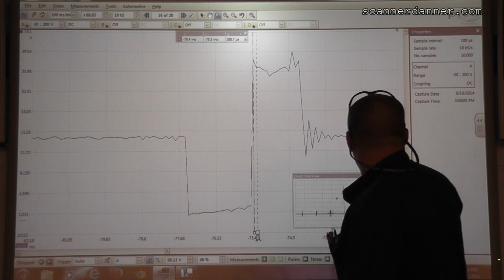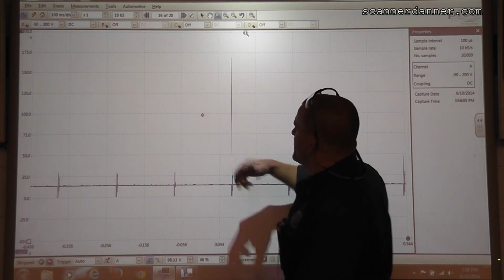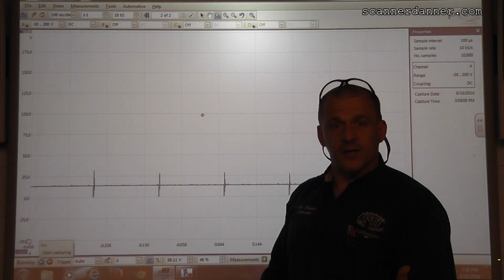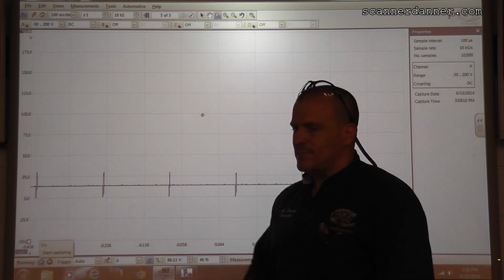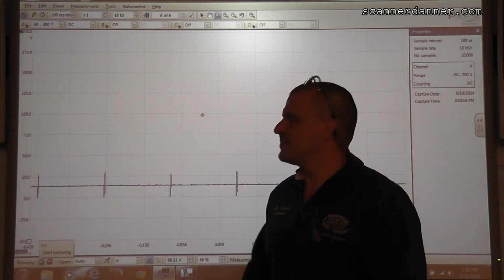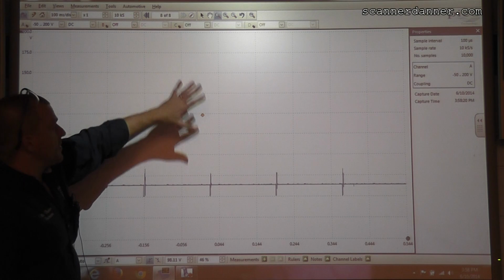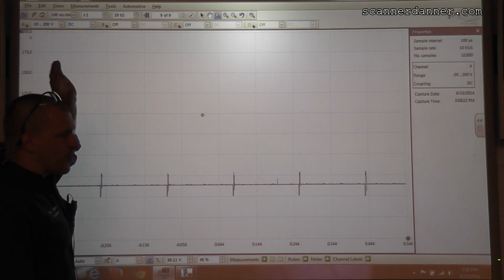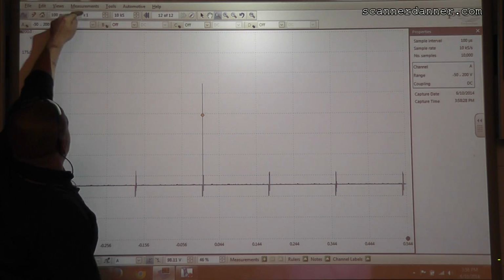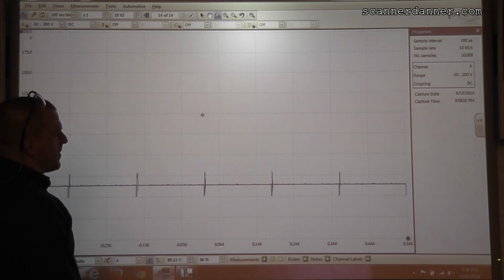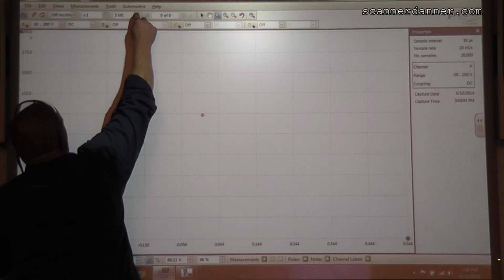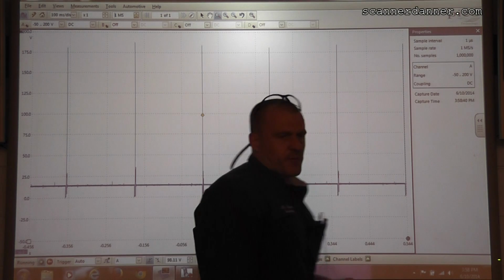I think we can appreciate that. All right, so what do we do then? If we want to take longer time bases, we need to consider increasing our sample rate. And while we do that, we need to also understand that we may eat up some of our buffer doing that. Not on these low numbers, we're not going to, by the way. We have to go over 1 million samples before we start eating up our buffer. All right, so this is 10,000 samples. Let's go back up to our default, that 1M, and you guys tell me if we're missing any detail now.